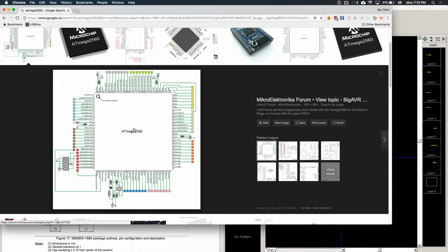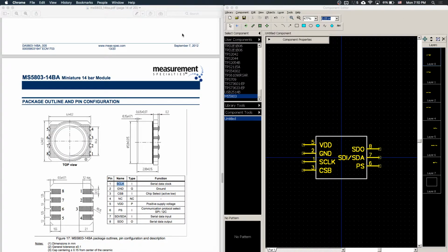If you go by function, you'll make your schematic better. But if you go by the physical layout, then you get some small insight into how you can implement the physical layout when you're doing the PCB. So there are trade-offs.